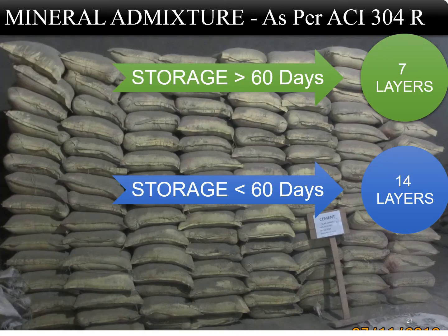Bags of mineral admixtures should be stacked on pallets or similar platforms to permit proper circulation of air. For a storage period of less than 60 days, stack the bags no higher than 14 layers, and for longer periods, no higher than 7 layers.